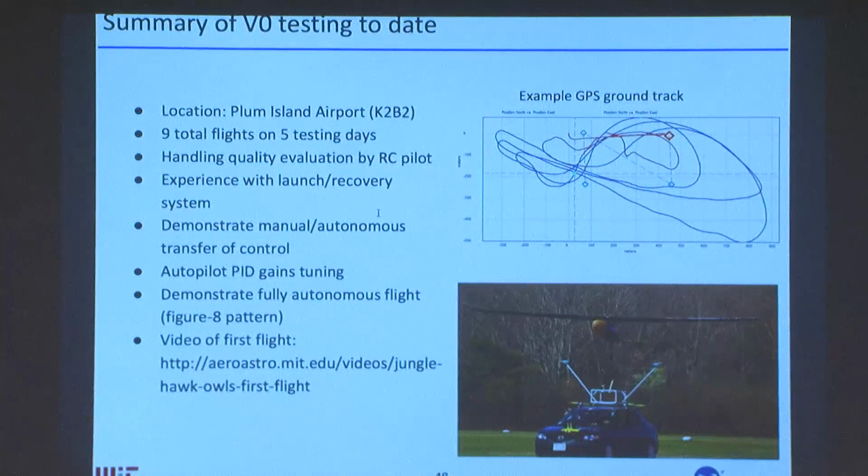We've tuned the PID. PID stands for proportional integral derivative. That's a type of control law you can use. That's what the autopilot uses to actually control the vehicle. So we're tuning the gains of those controllers. We've demonstrated fully autonomous flight around in a figure-8 pattern.